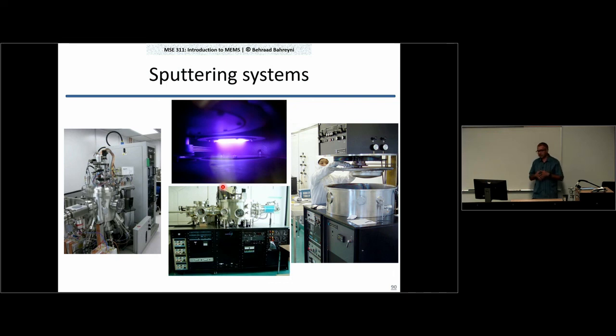As we said, this is a technique that you use to deposit materials other than oxides onto your substrate. Now the issue is that you're still limited to whatever your source has, right? So if you have an aluminum source, you're only able to sputter aluminum. If you have a gold piece, you can only evaporate gold. Your choices when you have a physical process are limited. You're not coming up with new materials. Whatever you start with will basically end up on your substrate, transferred from your source to your substrate.